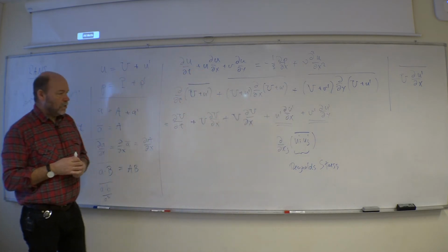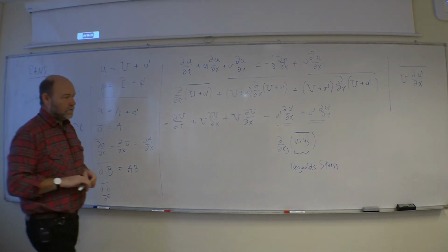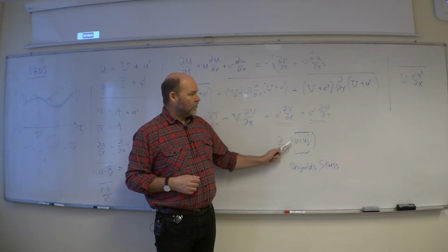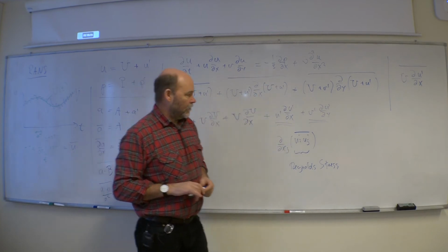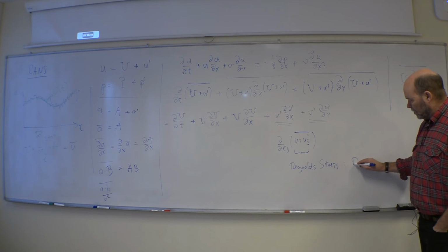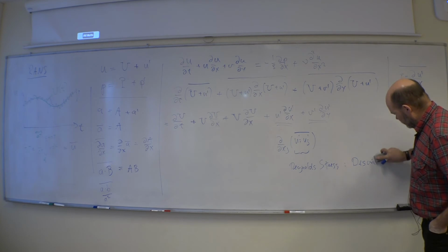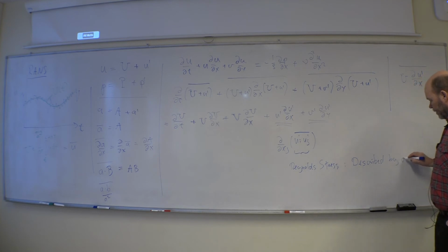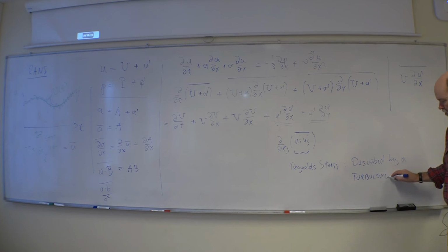So a turbulence model in the family number 3 is how to describe these Reynolds stresses, how to get a number inside the Navier-Stokes for these guys, now belonging on the other side of the equation system. Reynolds stress described by a turbulence model.